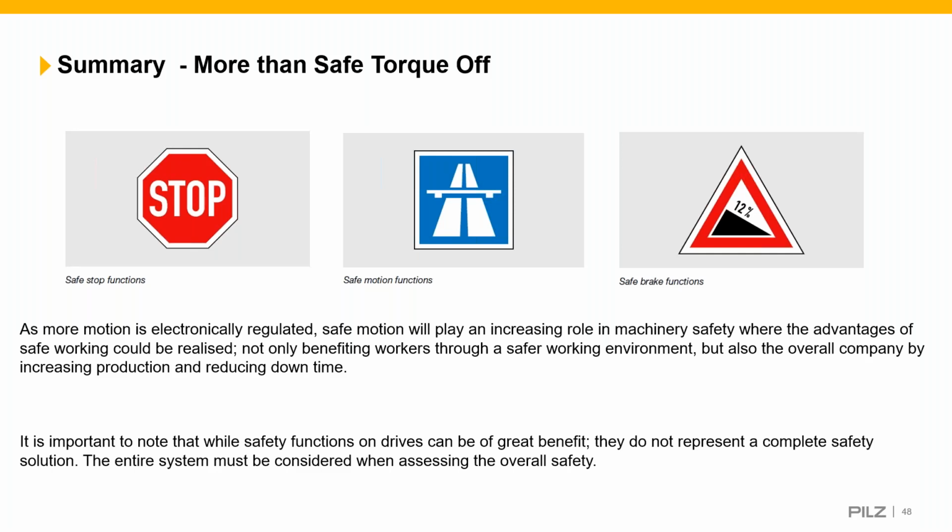No, it doesn't necessarily. In very few applications does safe torque off actually meet the requirements of the standards. So in this case, it's always best to actually look into this in a bit more depth. Is braking required? Does the inertia need to be held in order for it to be safe? And certainly where safe speed monitoring and safe speed is being used for loading or as part of the process and in interaction with the operators, it's extremely important to consider these aspects.